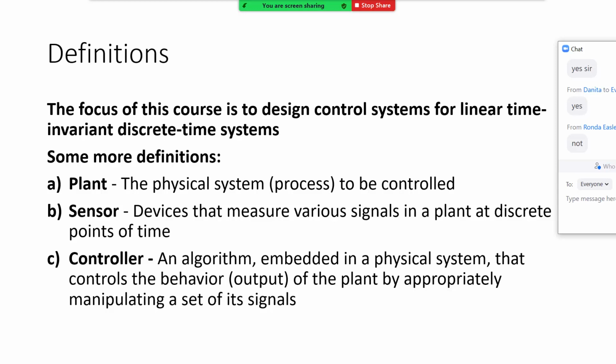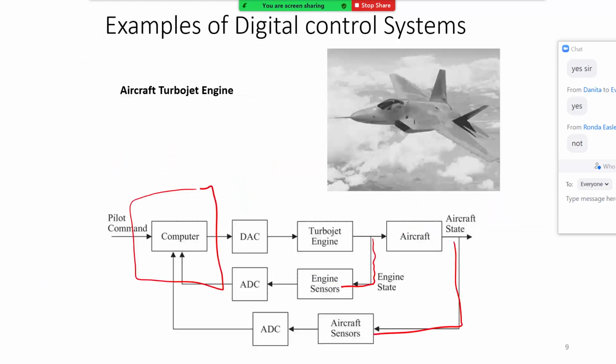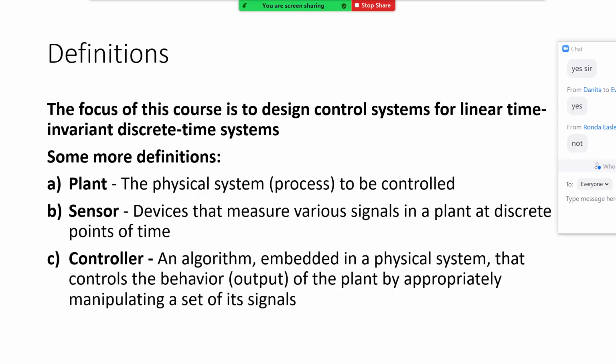And usually, if you remember the feedback loop that we looked at, where is this loop coming from? It's coming from a sensor. So this is my sensor. It takes a measurement of the output and feeds it back. Does anybody remember what we said in linear control about what is different about sensors? Okay, I'm going to tell you, and keep that in mind. Sensors are usually very fast, so they almost act instantaneously, and therefore they do not have any dynamics.